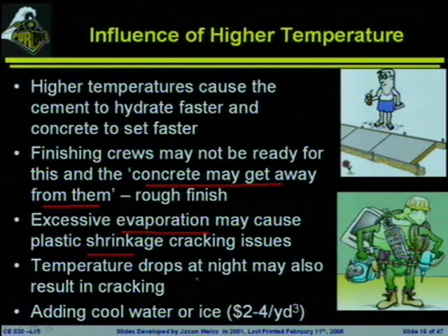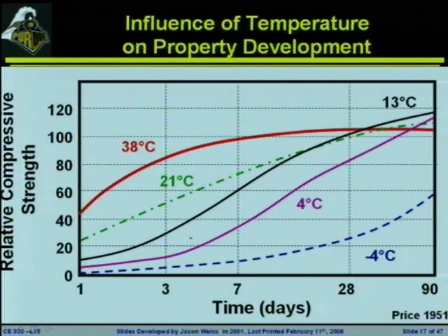And one of the biggest issues here is if it's really hot during the day, and the temperature drops down at night. That is really symptomatic of where you're going to get a big problem. If the temperature drops very quickly at night, the surface of the concrete is going to be very cold. The core of the concrete can be very warm. That temperature differential in the concrete can cause it to crack just on the temperature in the system alone. Typical rule of thumb is something around 18 degrees is a significant enough temperature difference that can cause cracking in just about any mixture. Question, Mike?